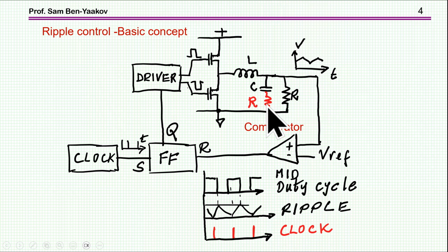Now the voltage of the midpoint here is a reflection of the output here, and I'm multiplying it so that I can get various levels. Typically it'll be like 8 or 20 volt, just to look at different duty cycles. I'll talk about it later on. Now I've also added here a current source to emulate a step in the load of 1 amp. It's running actually at 1 amp because 5 volt and 5 ohms, so it's a 1 amp load, and then I'm adding here another 1 amp during this transition.